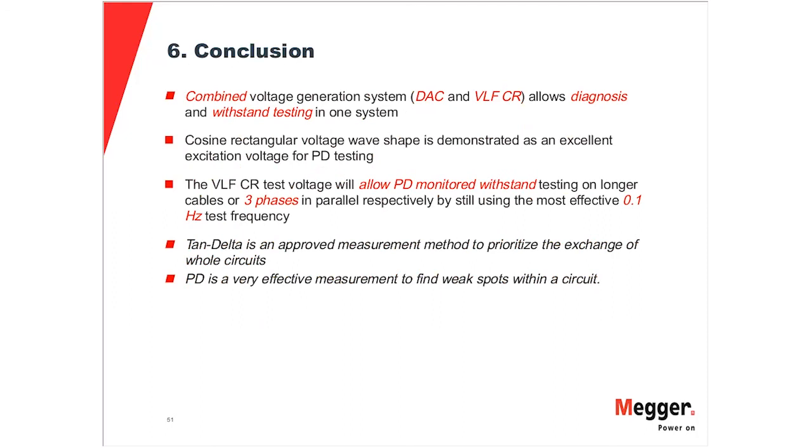The VLF cosine rectangular test voltage will allow PD monitored withstand testing on longer cables or 3-phase cable, so that you can run the test in parallel on all 3 phases at one time, which is of course extremely time saving and therefore also very cost effective.